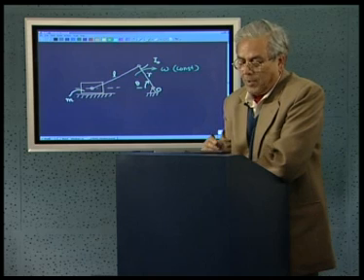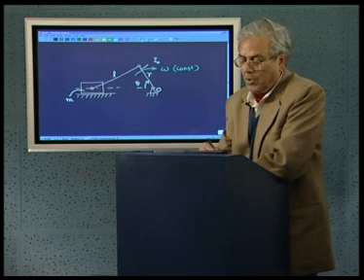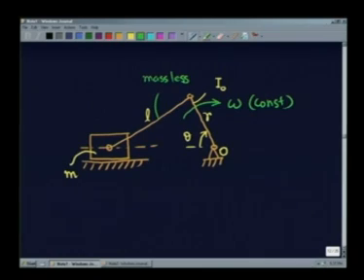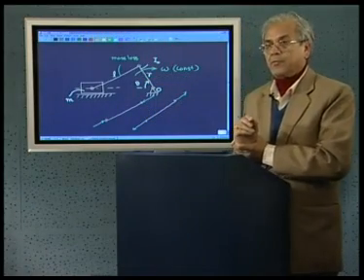Now, what we will do is consider this particular rod, if it is massless, for simplicity. Then it will be subjected to either pure compression or pure tension, which means that the resultant force on this will be 0, because it is a massless system, it cannot sustain any resultant force or moment.